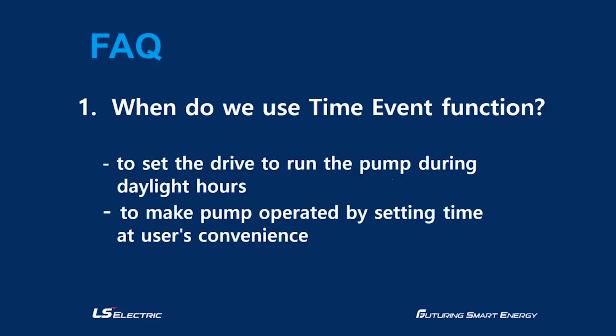Dr. Yoon? Time event function. Frequency start and stop can affect the pump negatively. So, if you set the drive to run the pump during daylight hour, the entire facility can be operated without being adversely affected. It is possible to make pump operate by setting time at user's convenience. I see. Thank you for the clarification.